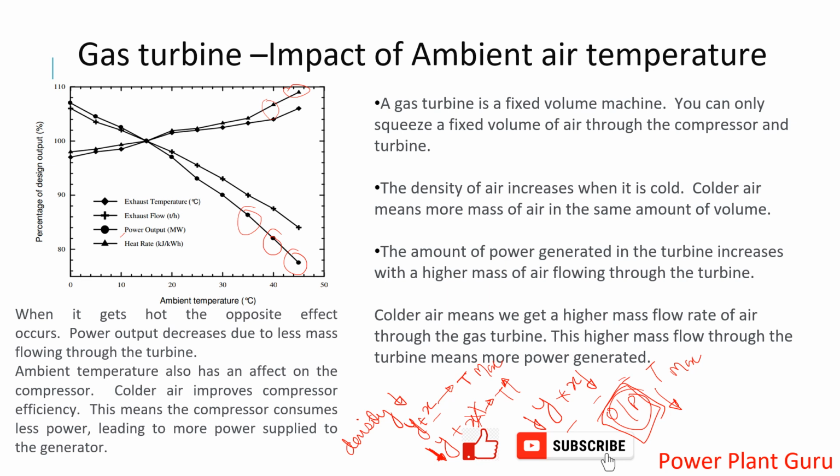If you calculate the compressor efficiency at this temperature, maybe 10, 20 or 30 degrees, the compressor efficiency is also impacted by the air temperature being handled. That is why your compressor efficiency is decreasing with increased air temperature. You see, cold air increases compressor efficiency. So that temperature factor is also there.